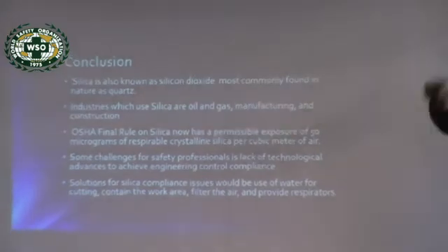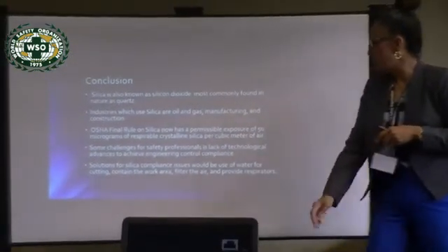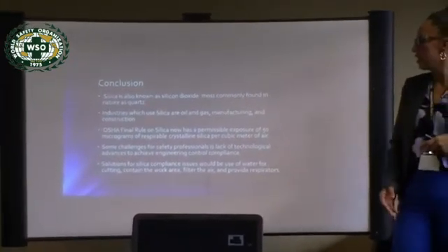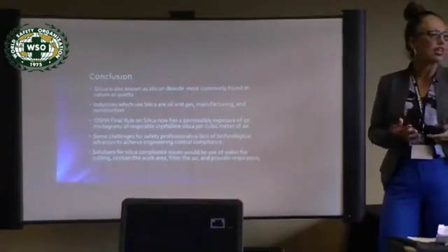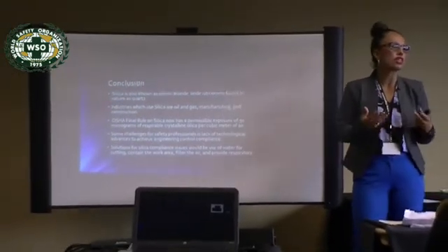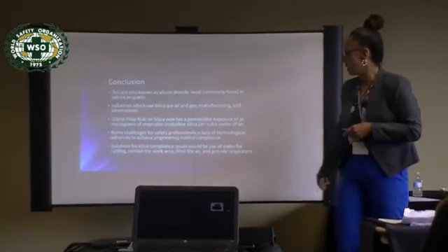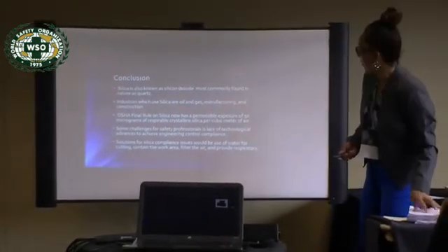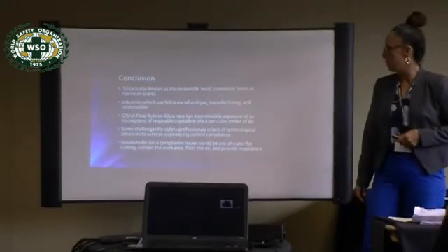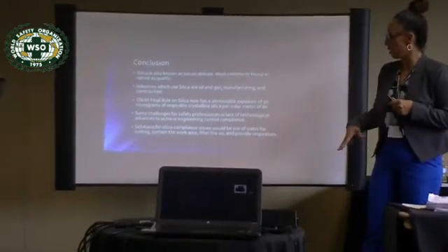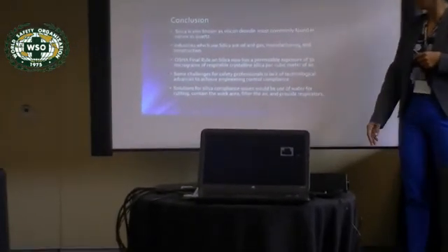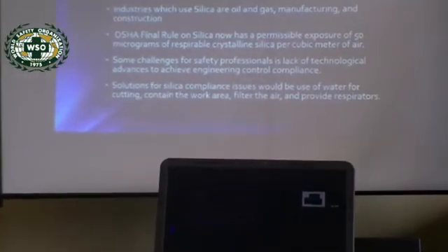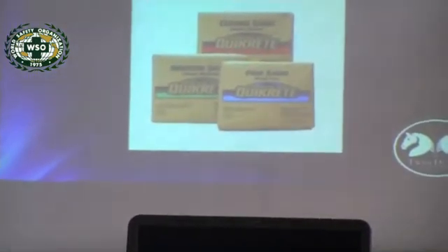Is it respirable? Also, some challenges as a safety professional is the compliance. The technology is not there. How to set up the engineering controls. What are we going to do to protect our worker? And as well, is it economically feasible? It's another thing we have to think about. So solutions would be just wetting, use water when cutting, contain the work area, filter the air, and provide respirators as a last resort. Questions?